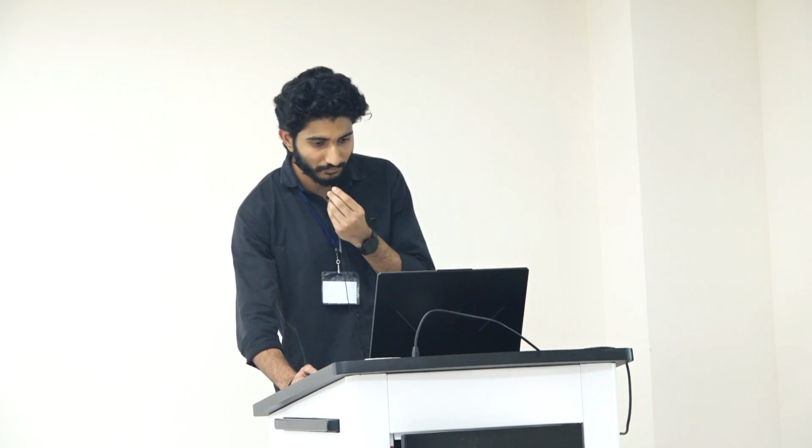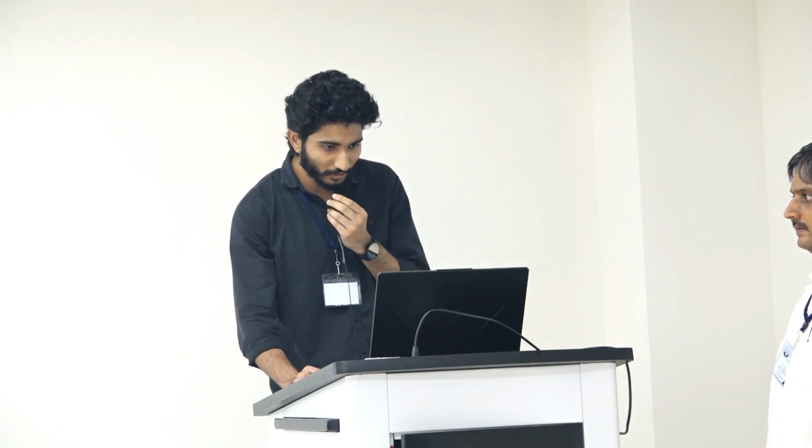So basically, in today's simulation section, we are going to discuss and design the nonlinear controller to control the output voltage of our DC to DC DAB converter. The converter we are using here is a dual active bridge converter, and the control technique that we will use is FIT-SMC, which is fast integral terminal sliding mode controller. So first of all, I will let you know what is DAB converter.